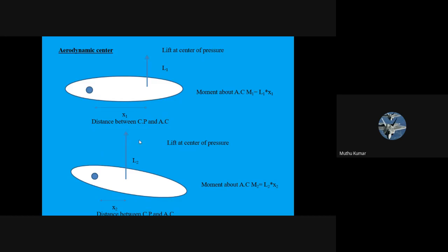கரெக்டா? இங்க ஒரு ஆச்சரியமான விஷயம் நடக்குது என்னோட ஏரோஃபாயில் மேல. ரொம்ப ஒரு ஆச்சரியமான விஷயம். என்ன ஆச்சரியமான விஷயம்னா, look at this. The lift force and the distance L1 into x1, a moment has created. When there is an increase in angle of attack, the distance has decreased, but the force has increased. இங்க என்ன ஆச்சரியம்னா, there is an m2 moment created right here. This m1 is equal to m2. The moment created about this point, this beautiful point present in my airfoil, it's a wonder point. Okay, it's a magic point அப்படின்னு வச்சுக்கோங்க.